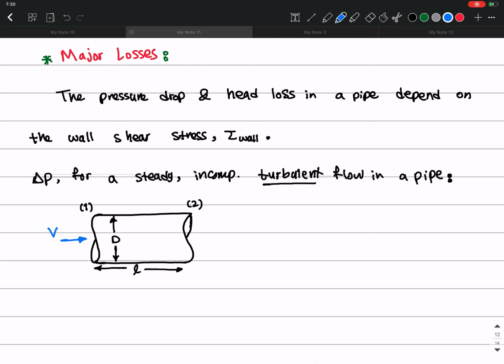Okay, so let's get a start with writing the first thing for finding the delta P using the Buckingham Pi Theorem, and that is listing all the relevant variables. So what is this a function of? Again, the fluid velocity is going to be important in the pressure drop. The length of the pipe is certainly important. The diameter of the pipe is certainly important. And the viscosity of the fluid is also very important, right?